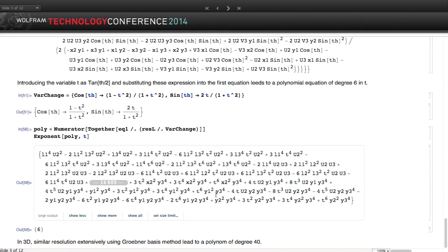So what is important here is this number: 14,600 terms. So that means that it is quite a big polynomial, and that it will be quite difficult to solve. And we are in the two-dimensional case, we are only interested for the experiment in the 6-dimensional case. Solving the direct model of such a robot has been made for the first time, I think symbolically, between 90 and 95. And it has been made with a lot of Gröbner basis computation.